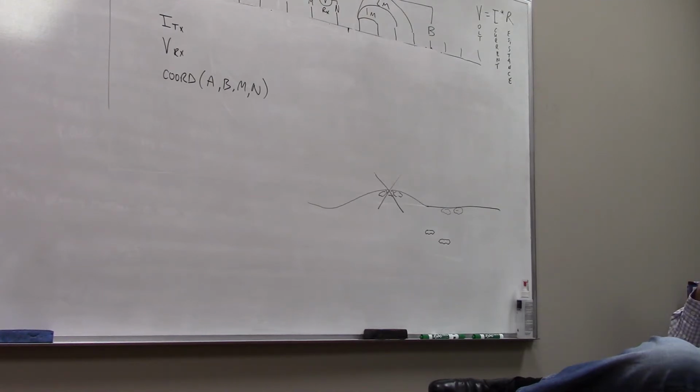I think that you just have to do some ground truthing. Do some measurements and see. Then come back with your normal type of exploration. You just go start pumping and see where you get stuff, and then you can look back at your image and you say, okay, I think it's really associated with these locations, more conductive areas, for example, and more resistive areas, or structure.